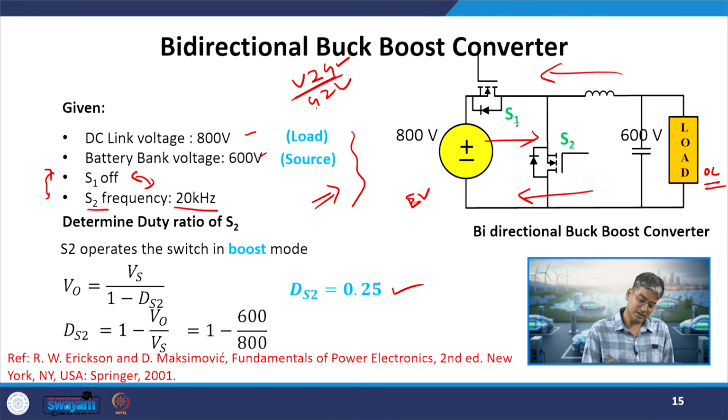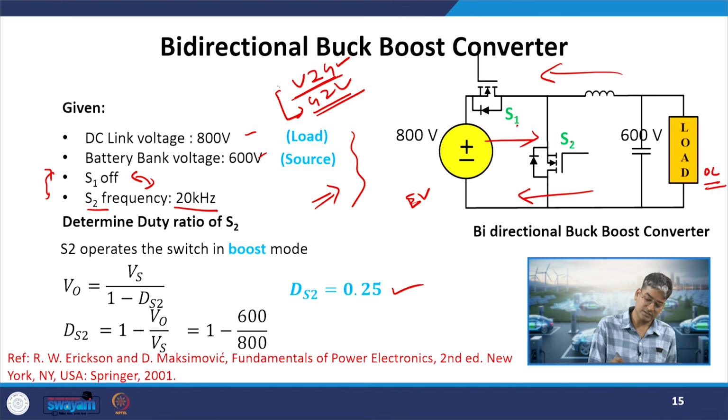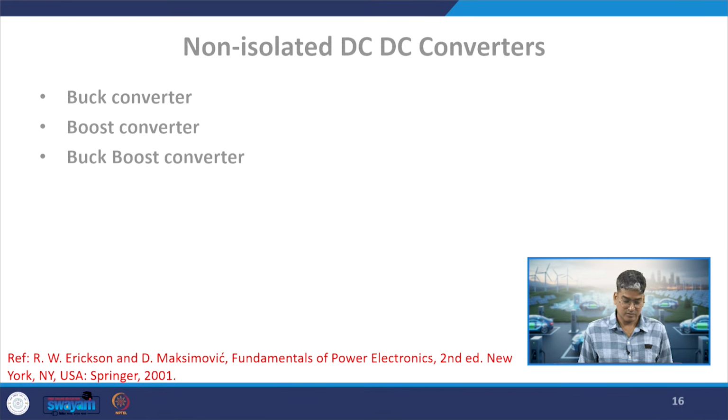The other mode, the normal mode of operation, is grid to vehicle, where the vehicle is getting charged. So when I want this type of bidirectional feature in the charger, I will be using this, and on board we will always have a bidirectional feature requirement, because we will have some excess energy in the motor which can be recovered and used to charge your electric vehicle battery bank, which can increase the range, or it will be providing optimal use of the energy present on board.